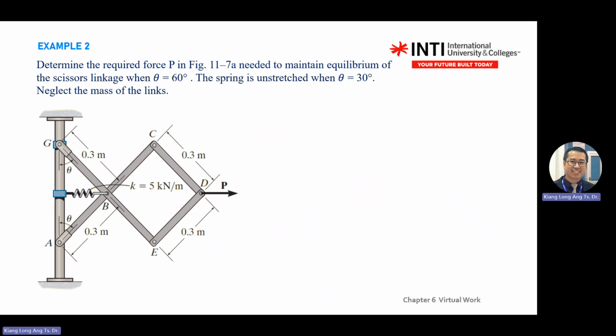When you draw the free body diagram, you don't need to write the full equation, but you need to be able to identify what forces we have, for example the connection force, the connector force, and also the spring force. After you do that, only then you go for the imagination. You predict the motion, then you observe what will do work in the diagram, then you solve for the equation.